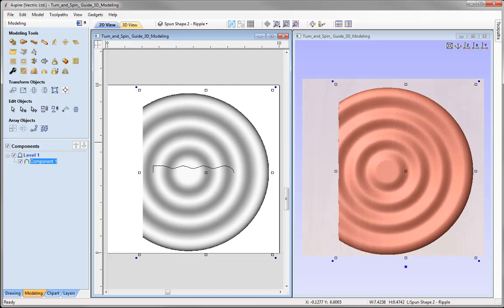And so it's important to remember here that the software will spin this about the left side of the cross section. So just make sure that your job space is big enough, or that you have your vector positioned in a way that the software can create the full circle for you.